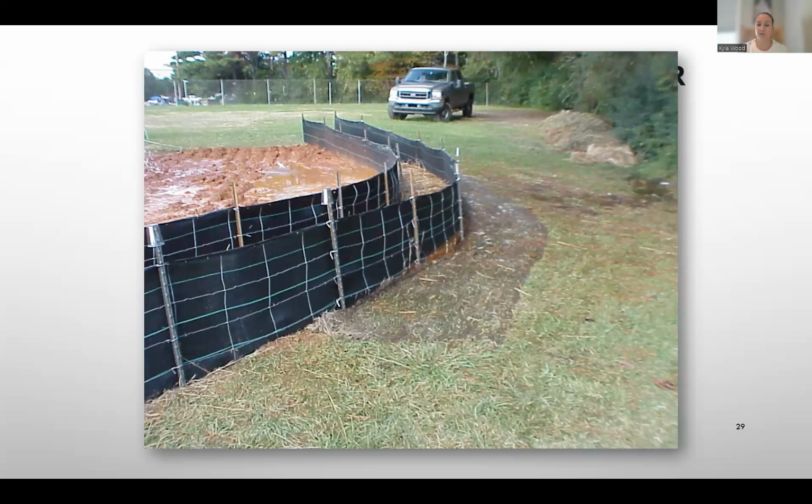Depending on what your rules are, in some places you're not allowed to use a flocculant unless you have a buffer zone, a sediment basin, or some type of particle catchment. So depending on the state rules of where you're at, it depends on where you can put these, but a lot of people will use these as a perimeter defense, to be a final line for water clarification.